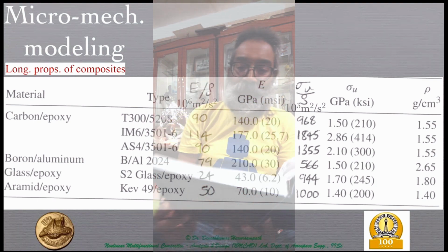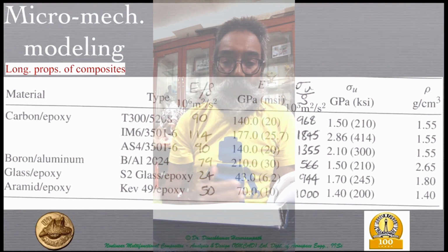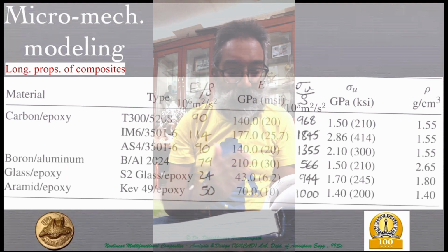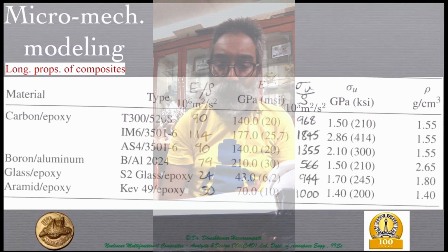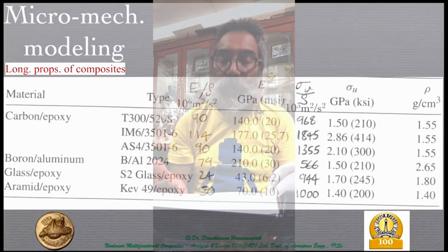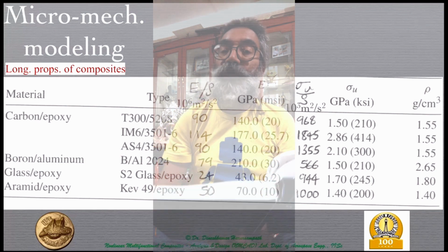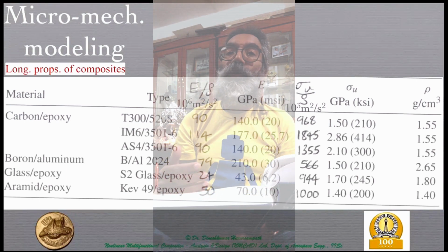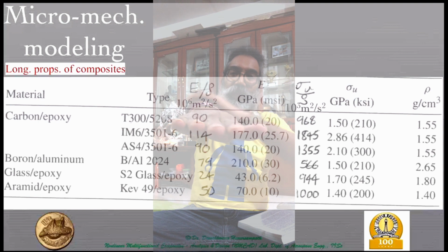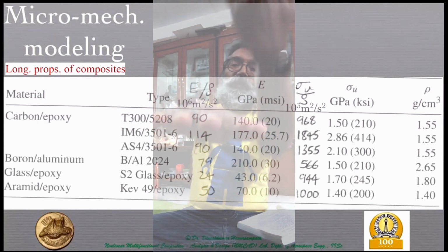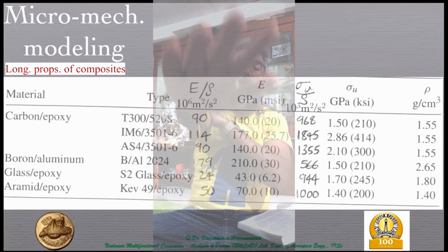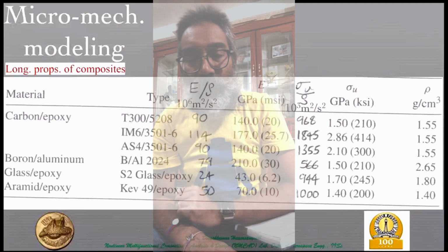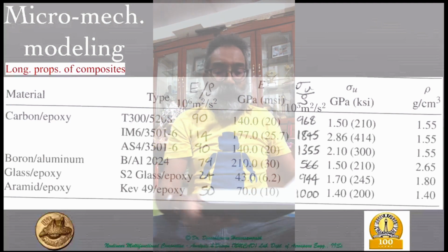Okay. So the 7075, on the other hand, has a higher strength of about 538 megapascals compared to 449 megapascals for 2024. And because of the higher strength, it can be used in certain applications which are, of course, this is a tensile strength, but in compressive strength, it's even better. So it would be used in those regions which are subjected to compression. So in the case of the wing, it's the top surface because of the lift being fairly large. So you have the top undergoing the compressive loads of the bending stress. So that is where the 7075 is typically used.